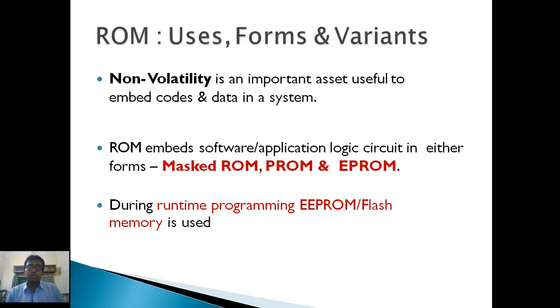ROM, read-only memory. Read-only memory is non-volatile, an important asset useful to embed codes and data in a system. ROM embeds software, applications, and logic circuits in forms such as masked ROM, programmable ROM, and electrically programmable ROM. Or for programming during runtime, EEPROM, or electrically erasable programmable ROM, and flash memory are used.